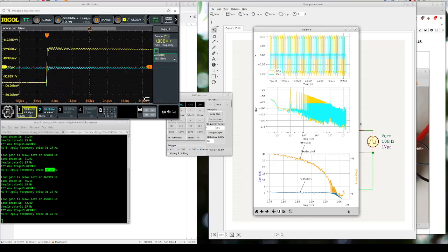Below here you can read the value. The x-axis is the same. The first couple of values is the phase, and here I put it at 44. So 45, it's a bit more. But actually the phase margin is more like here. So you can see noise can spoil the output, especially if it is very close to 0, like here. So do zoom in and use common sense.